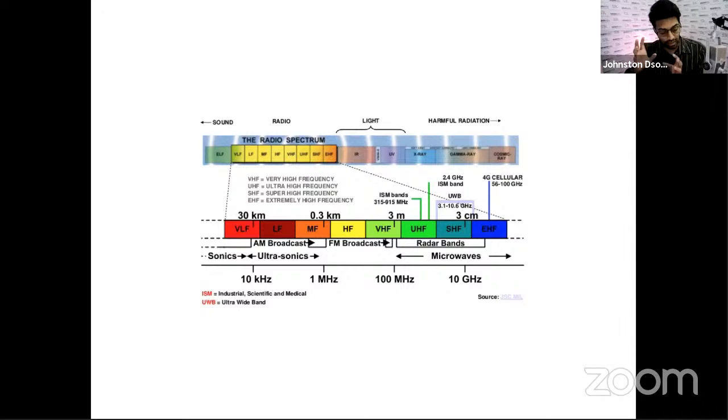So if we start using pro audio there, it will be difficult for us to find free frequencies, and we'll have issues with finding a clean frequency to transmit and receive on. So we use another unlicensed band, that is the VHF and UHF band. Now in India, we're using somewhere around 350 megahertz to about 500 megahertz, somewhere in between that. There are some bands which are auctioned off, but there are other free bands that are available for use.